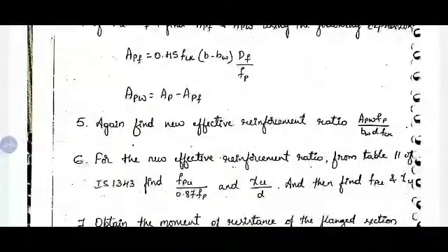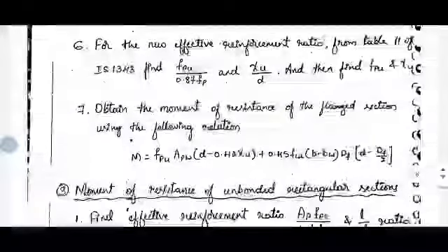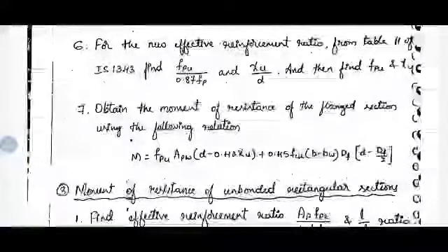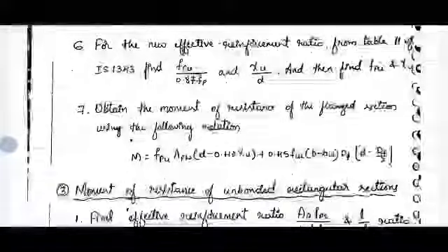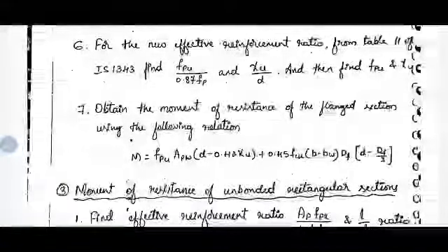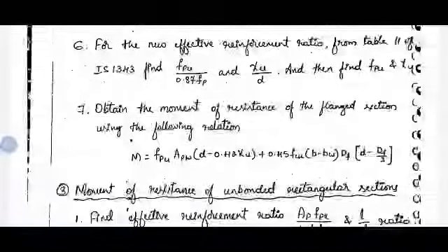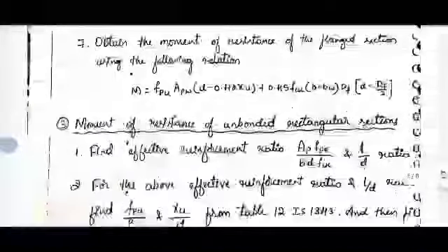Then again for the web portion we need to find out the new effective reinforcement ratio. Again for the new effective reinforcement ratio we need to find out FPU and XU. Then we need to find out moment of resistance using the formula. These formulas are available in the codebook. So these two are for bonded condition, bonded rectangular and bonded flanged sections.